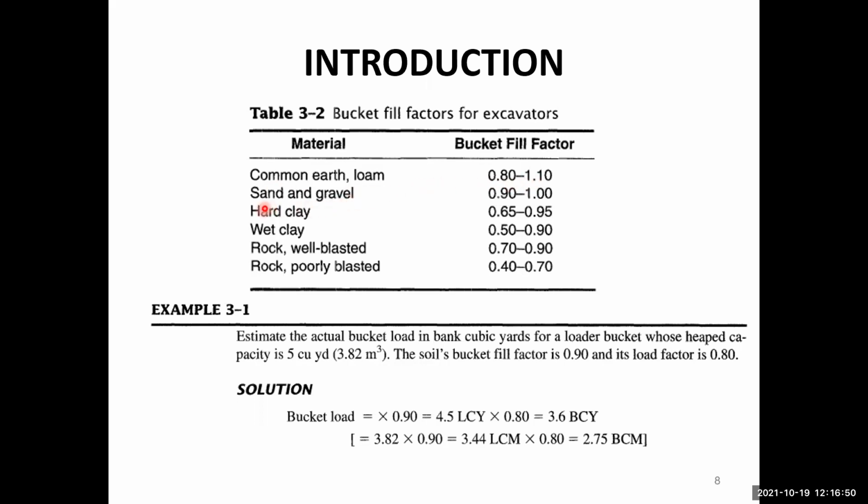If it is sand and gravel, the bucket fill factor may be taken as about 0.92. That means whatever the volume of the bucket, you can take this bucket fill factor and multiply it with that, and then you get the amount of load in the bucket at one time.